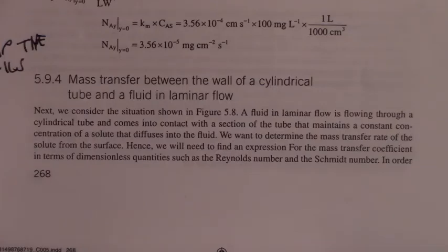I'd encourage you to look through the math. On the blog in that section, the Chapter 5 stuff, there are a couple of additional information sheets that talk about the derivations of some of the equations in this particular section. But what we really want to get to is a correlation for the Sherwood number that would allow us to calculate the mass transfer coefficient for laminar flow in a cylindrical tube. In this case, in order to get an analytical solution, we have to make an important assumption, and that's going to be the short contact time solution.